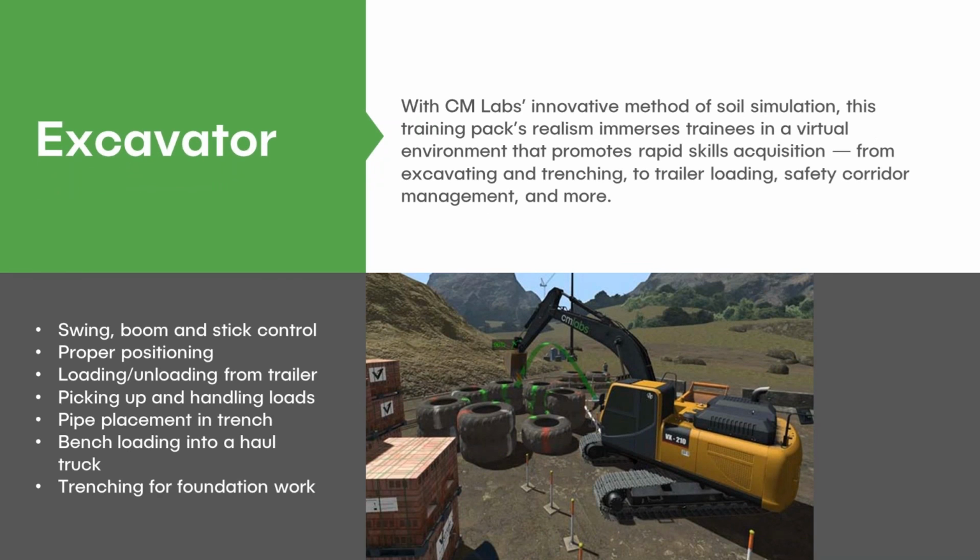The excavator, 21 ton. Basically that's the workhorse. That's the one where you're understanding. You can have the two different control schemes, whether your ISO or SAE standards. You can switch those on the fly. Lots of practice on where to position your bucket, how to trace it along the arc, how to work with suspended loads, how to put some pipe down into a trench, how to make a trench, how to dig out a trench box.